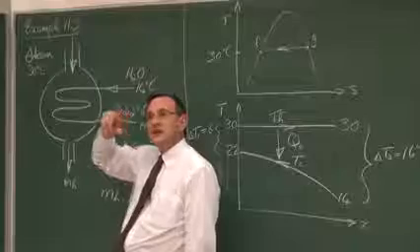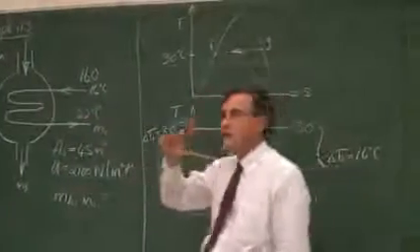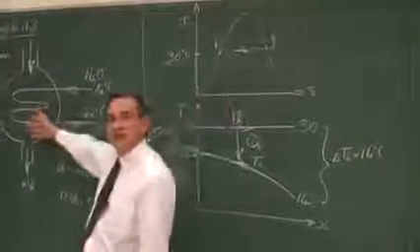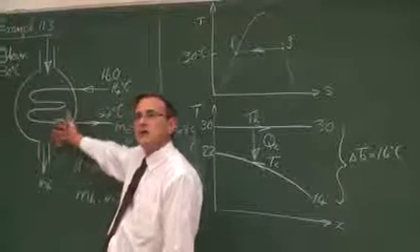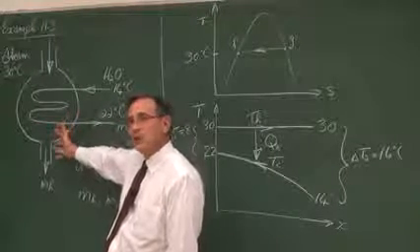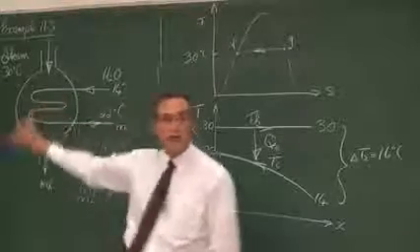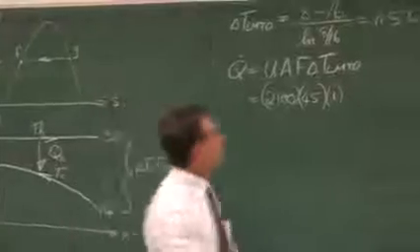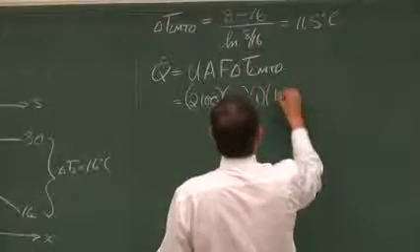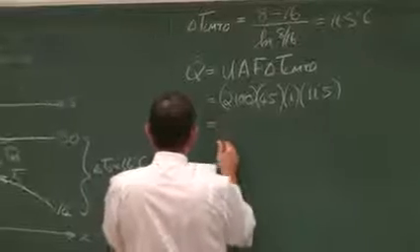Now in that, we've got an R or a P, and the delta T is going to be 0 or infinite in one of those two terms. So we've said in general, the moment we've got boiling or condensation on one of the streams, then F is equal to 1. Okay. Multiplied by the LMTD, which is equal to 11.5,